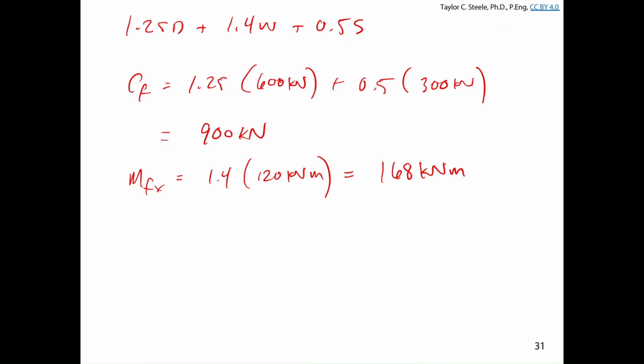The one question I'll ask, though, we have a smaller axial force. Is that going to make U1x bigger or smaller? Remember that U1x is accounting for the additional moment from the axial force. If the axial force is smaller, there's less additional moment. U1x should be smaller. Right?